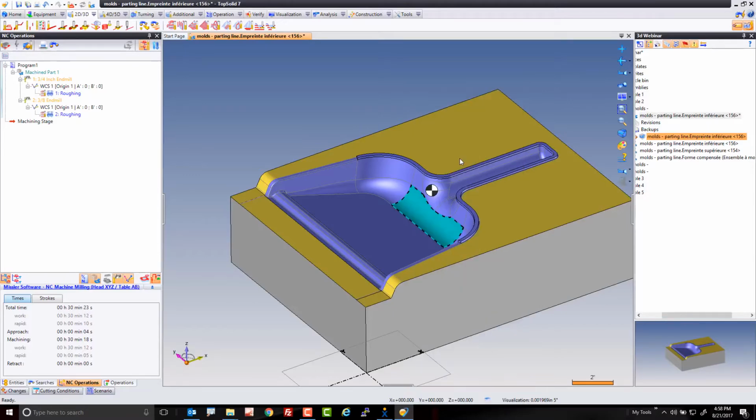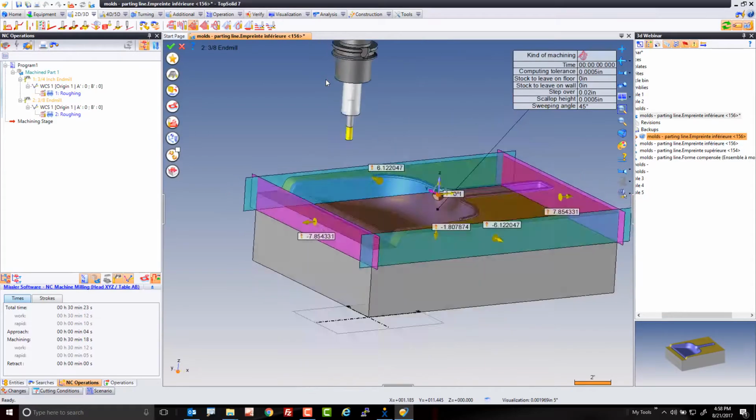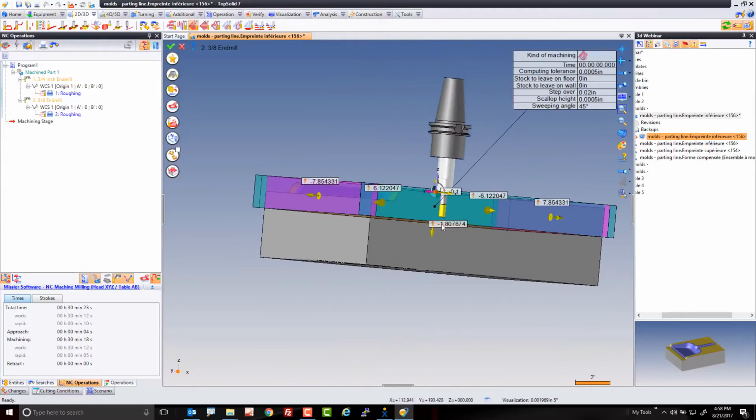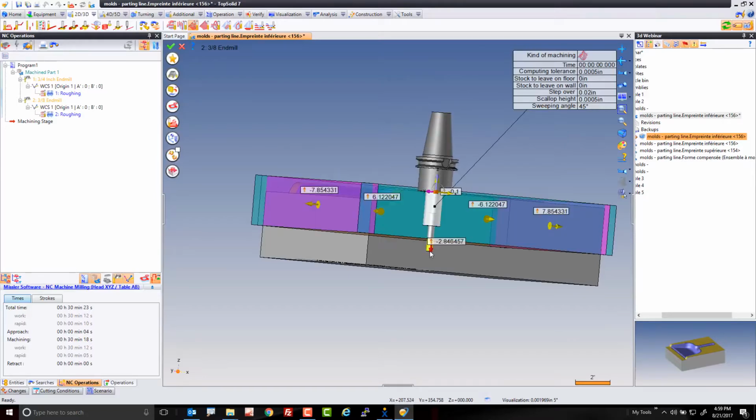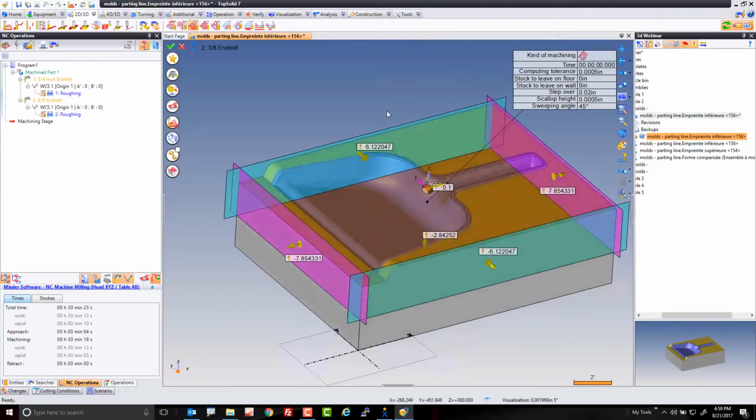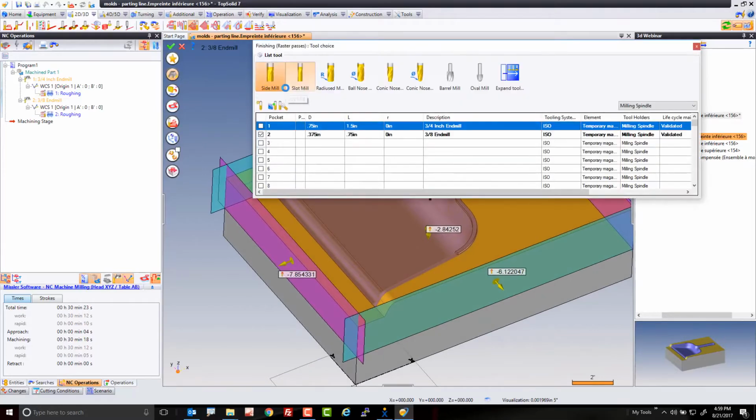So if I go to finishing, for example, you'll see my planes pop up, and they're popping up roughly to the bottom-most Z of the face selected. It's kind of a neat little magic trick. You can always move that down or up and play with this as you want, type the value in that you want. Here I'm going to, again, grab a tool.